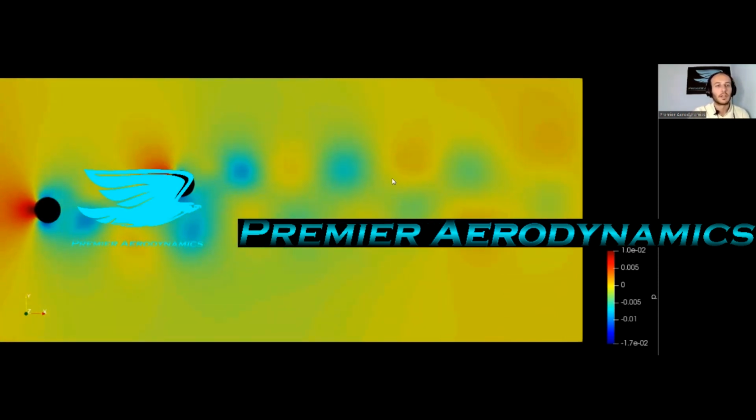And in the downstream pressure, you can see that there is a bit of a weaker core for this bottom series of vortices. That's because of this upstream cylinder there. These vortices are canceling out. The top vortex is canceling with the bottom vortex, so you don't get much of a low core compared to the top vortices.